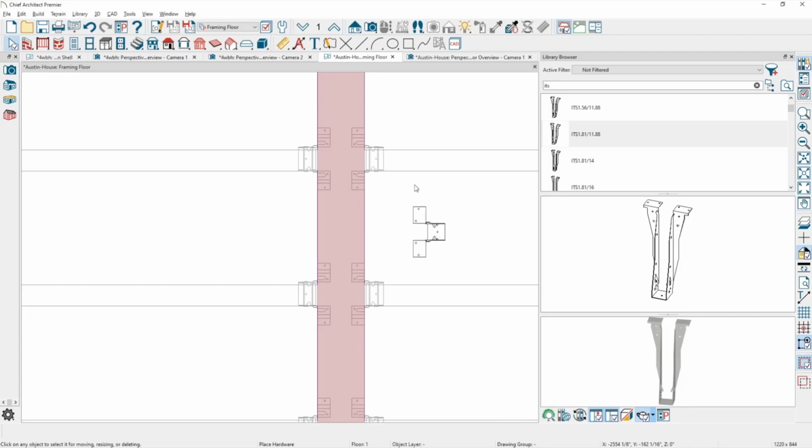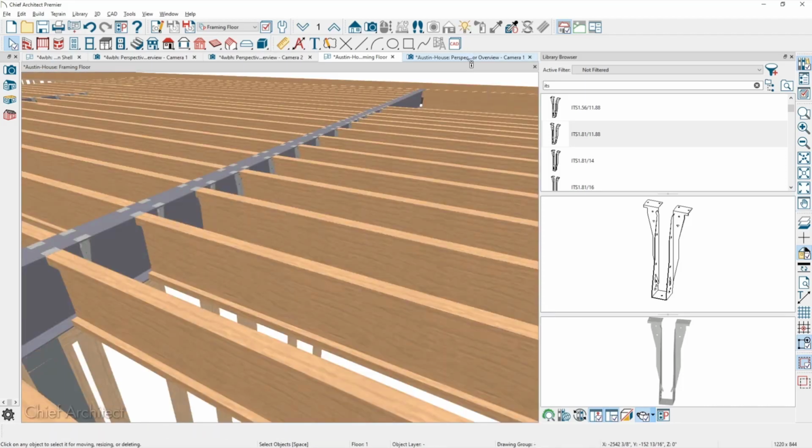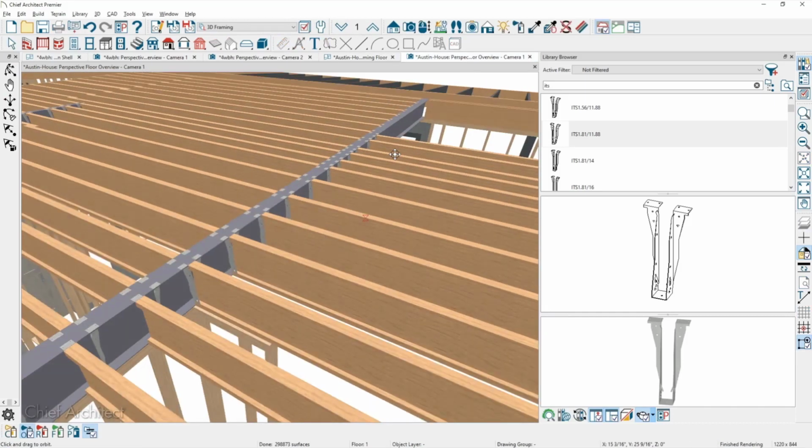And in this case, if my joists or my trusses are on 24-inch on center, then you use a multiple copy reflect around the beam, and that's how you might do that. But there is no automatic way to place those on this structure. Okay. Well, that would be a good feature add. Okay, we'll make note of it.